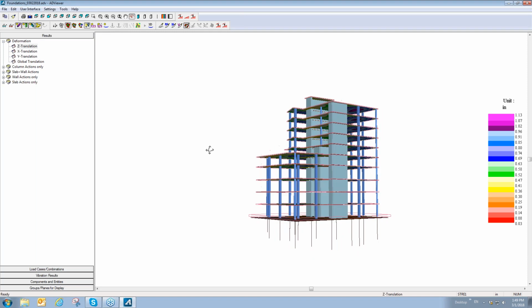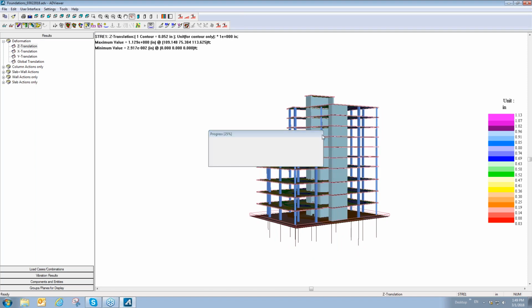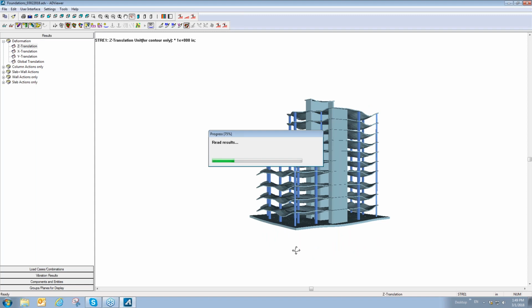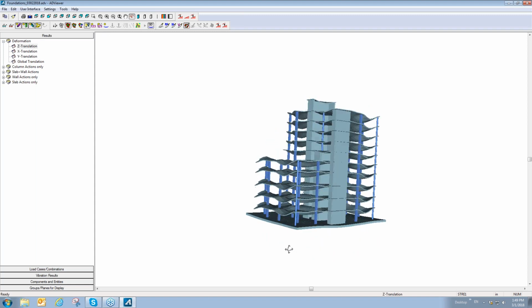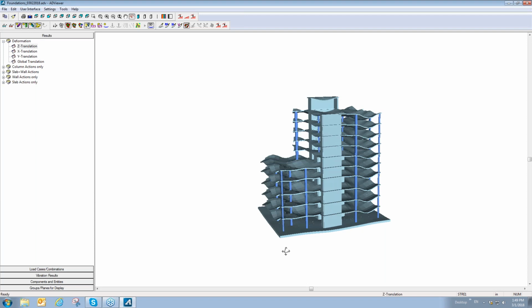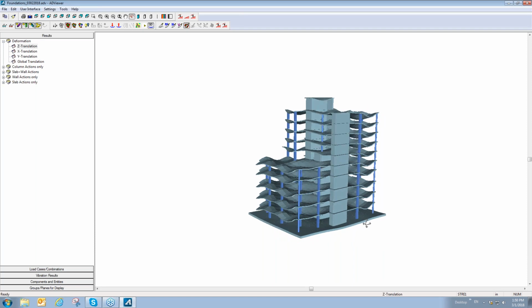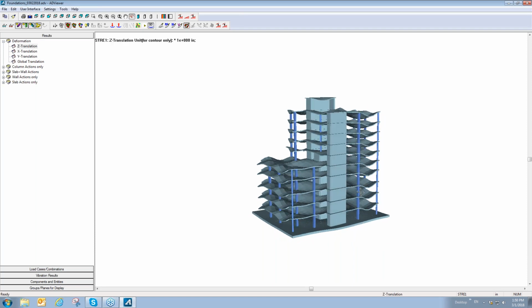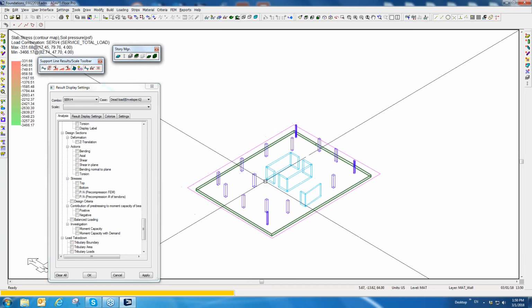I'll turn off the values, turn on the contours, and you can see this whole building is just sagging downward because the bottom is able to displace in this analysis run, which tends to pull the structure down, which induces additional forces and moments in the slabs above. So you'll actually get more displacement at slabs in this type of run than you would in substitution, because the program accounts for that displacement and the instantaneous axial deformation in the columns as well. Those build on each other and cause, I'll call it, magnified displacements or actions above.